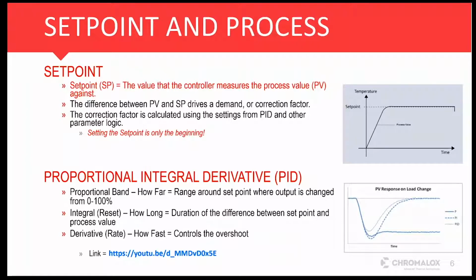We explain how that correlates to the set point, how we work through that, and more importantly, how the PID loop in the controller works. You've got your proportional band, so think of how far, how long, how fast. That's where your ramp up time gets calculated and recalculated, actually, with the auto reset and the timing to avoid overshoot. You think about dialing it into the degree. We can do that if the settings are correct and you know what to look for.